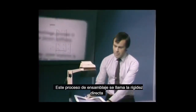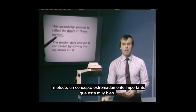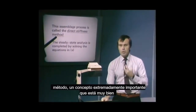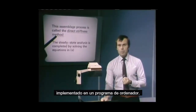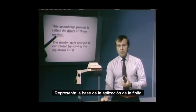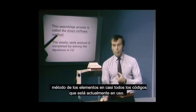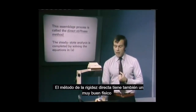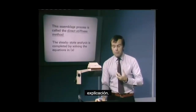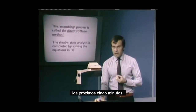This assemblage process is called the direct stiffness method. It is an extremely important concept that is very well implemented in a computer program. It represents the basis of the implementation of the finite element method in almost every code that is currently in use. The direct stiffness method also has a very nice physical explanation, and this is what I really want to talk to you about for the next 5 minutes.